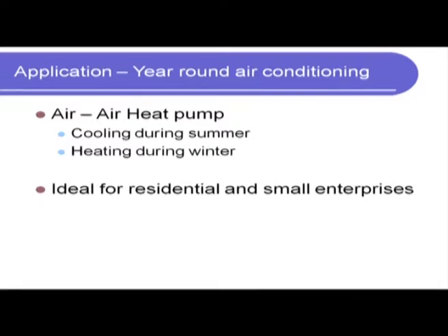If you recall, yesterday we started with our discussion on heat pumps, what a heat pump is, essentially the fact that it is a way of upgrading the quality of energy that is available to us at a low temperature. You upgrade that energy using a heat pump, and of course it does not come for free. We use a vapor compression cycle, which is a normal refrigeration cycle, except here the difference between refrigeration and heat pump is our aim is to have thermal energy at a higher temperature compared to refrigeration, where we remove heat at a lower temperature. But essentially the way the cycle works is the same.